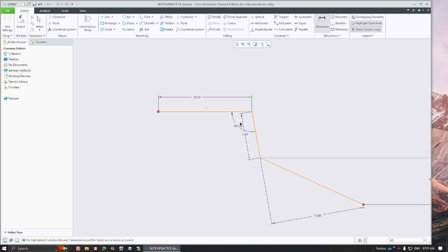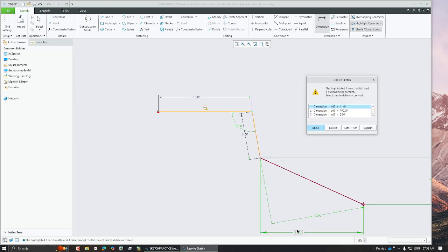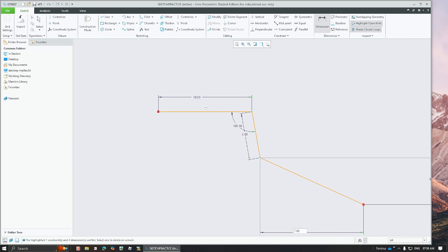So now, because I have deleted the vertical dimension, this line is getting modified. And while this is happening, you can see the length here. This was not a horizontal length, this was the distance of this point from this line. So if you want exactly a horizontal distance, you have to again choose the dimensions, click on these 2 points and click extremely downwards or extremely at the top. So this will create a horizontal dimension. I don't want this, delete it, and you can define this.